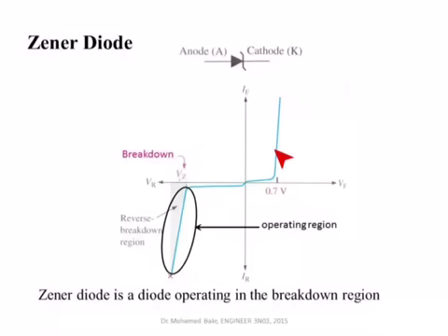It can really take any value. This line can be a vertical line, or we can take into account the resistance, so we can have a resistance in series with the equivalent voltage source. But effectively, once it turns on, the current through it is determined by the external resistors and components of the circuit.